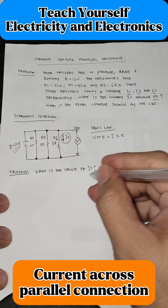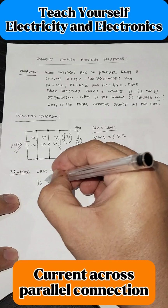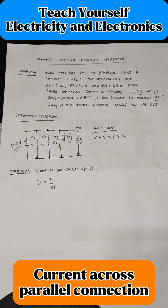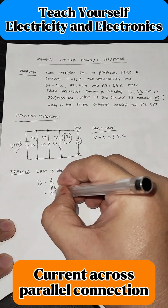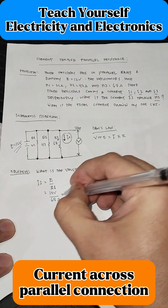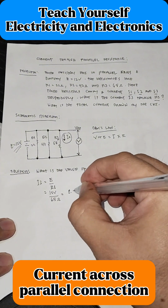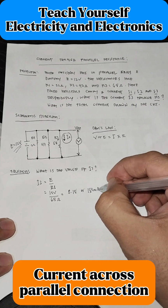So I3 equals E over R3. We have 12 volts over 68 ohms, which gives 0.18 amperes, or 180 milliamps.